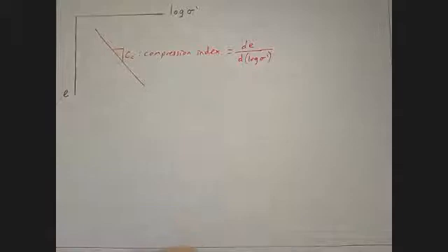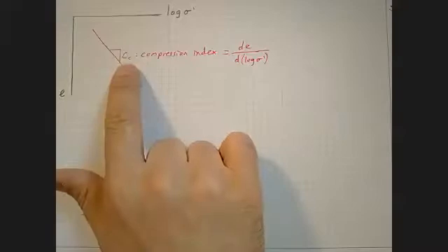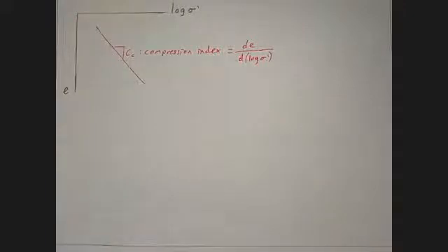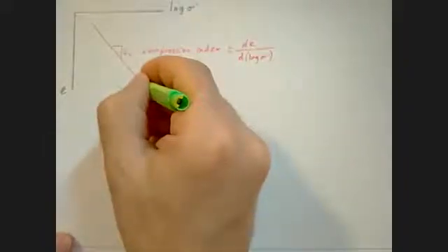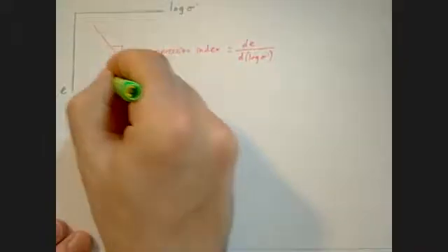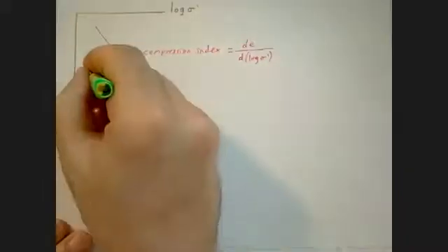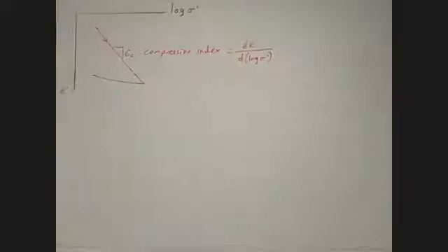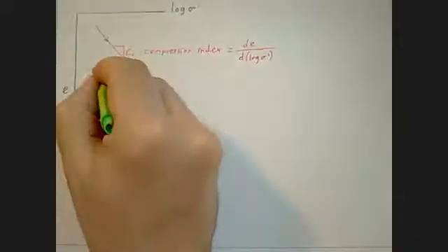Now, yeah, okay, this is nice. And again, you have a single parameter to model the compressive behavior, but actually it is not enough because then people noticed that this is not all that the soil does. The soil also does this. If you start from a point and unload it, it does this. So as you load, it goes like this, but as you unload, it goes like this.